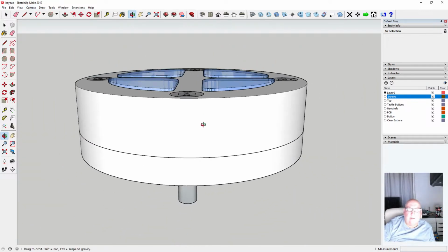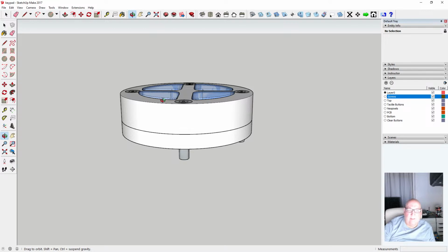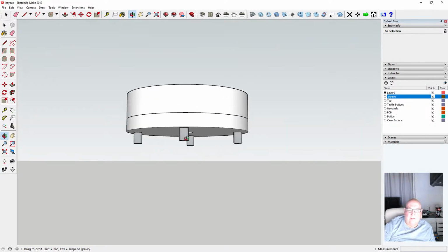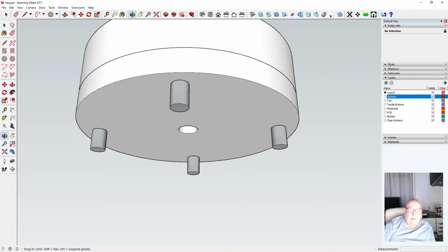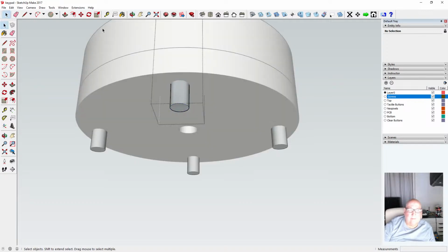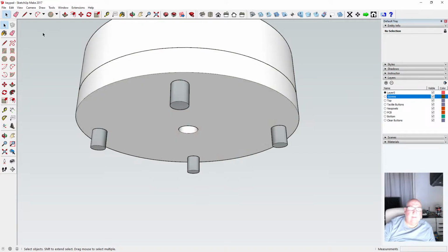The buttons now stick up by 0.6 of a mil, which is the action when you press them flush. The action required for the tactile button is 0.5 of a mil. So we said we want 5 mil sticking down here. We've now got 5.5 mil, so we've lost a bit of size off these. 0.5 of a mil. Okay.